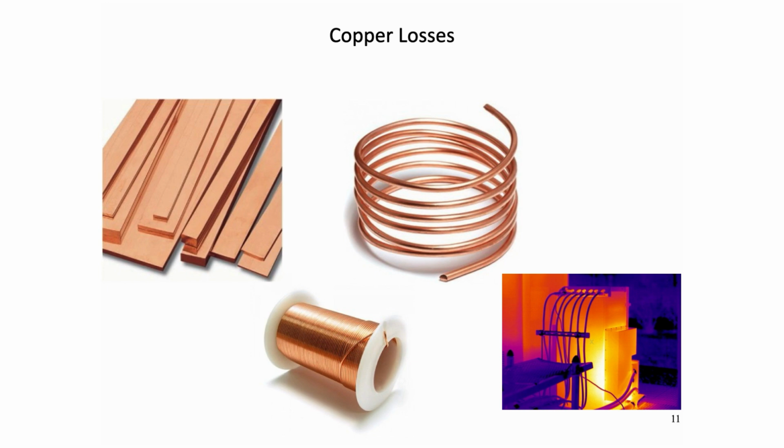A transformer's rating can be increased by better design and transformer construction to reduce these copper losses. Transformers with high voltage and current ratings require conductors of large cross-sectional area to help minimize their copper losses. Increasing the rate of heat dissipation through better cooling by forcing air or oil, and or by improving the transformer's insulation so it'll withstand higher temperatures, can also increase the transformer's rating.